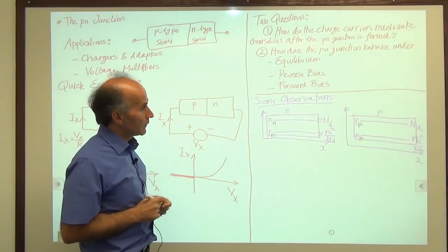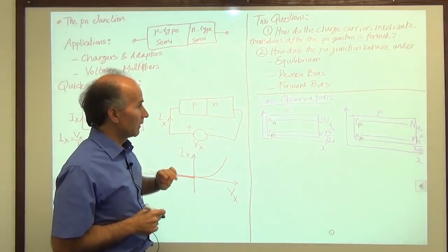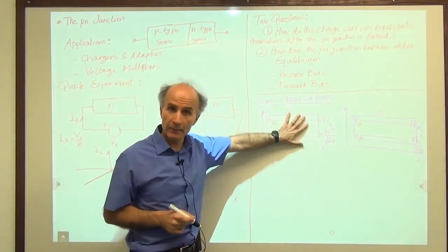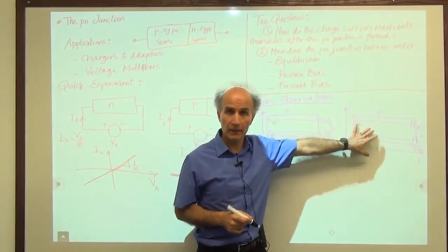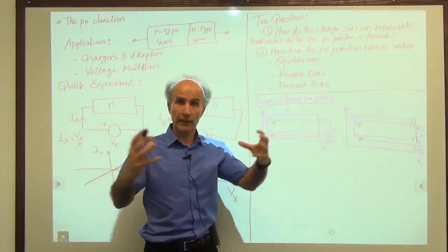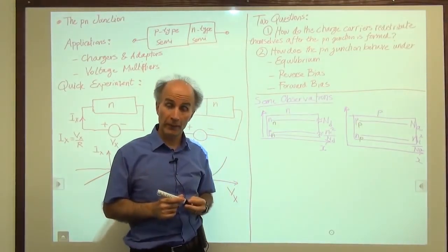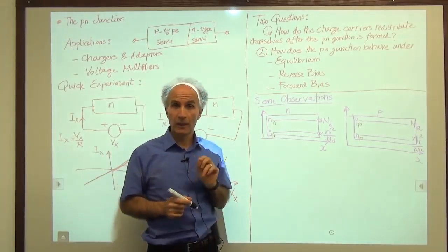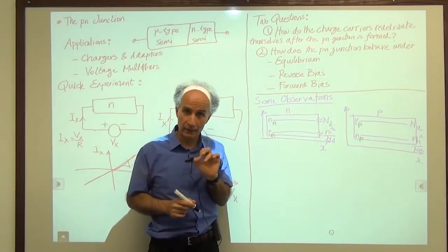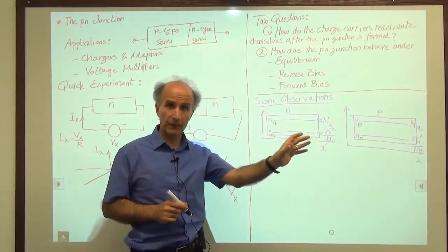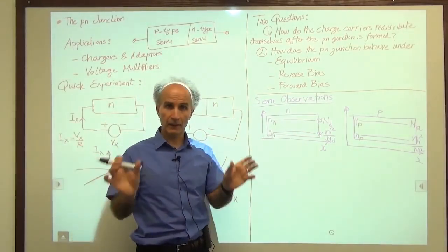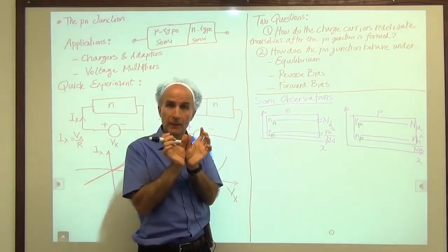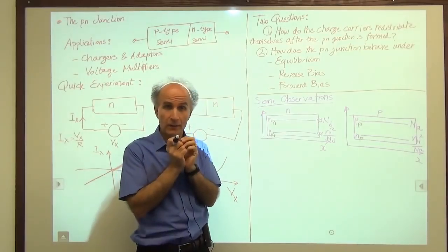Very well. So that is the situation when I bought a piece of N-type silicon and a piece of P-type silicon, and then I'm ready to attach them to form a p-n junction. Now, I should mention that if somehow you go and buy a piece of p-type and a piece of n-type silicon and try to attach them, you will not have a p-n junction.